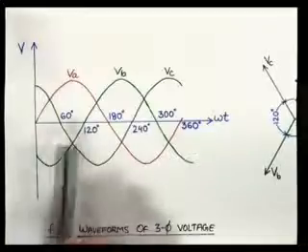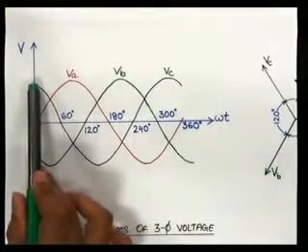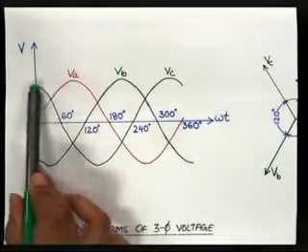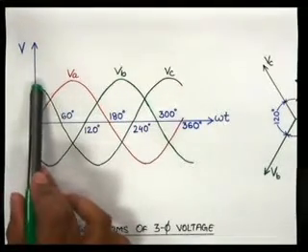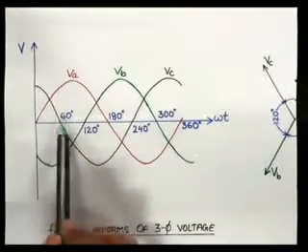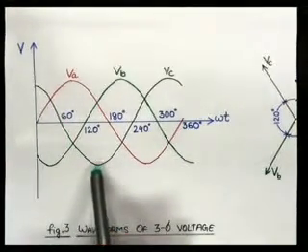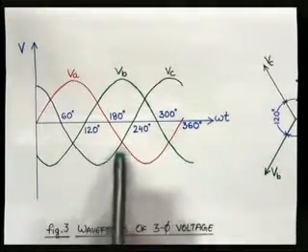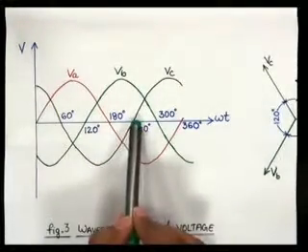At the same instant, the voltage across coil C, that is VC, has just passed through its maximum value. Some EMF is induced in the coil VC. It is decreasing. It is coming to 0. Further it's decreasing. It's reaching its maximum peak value in the negative direction. Again coming to 0 and so on.